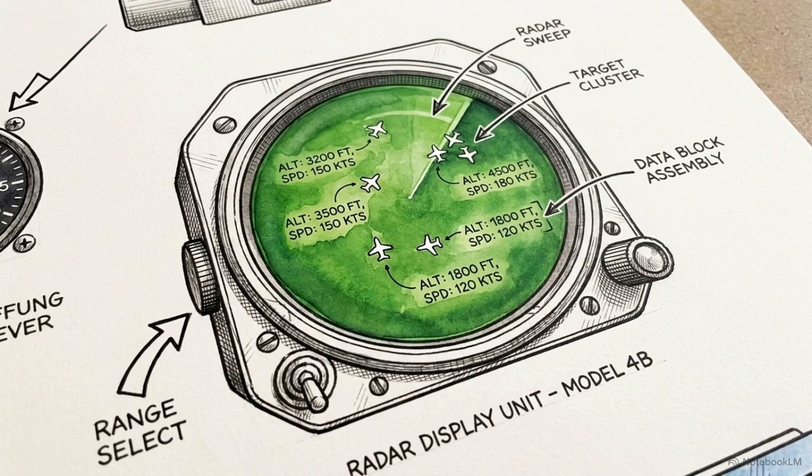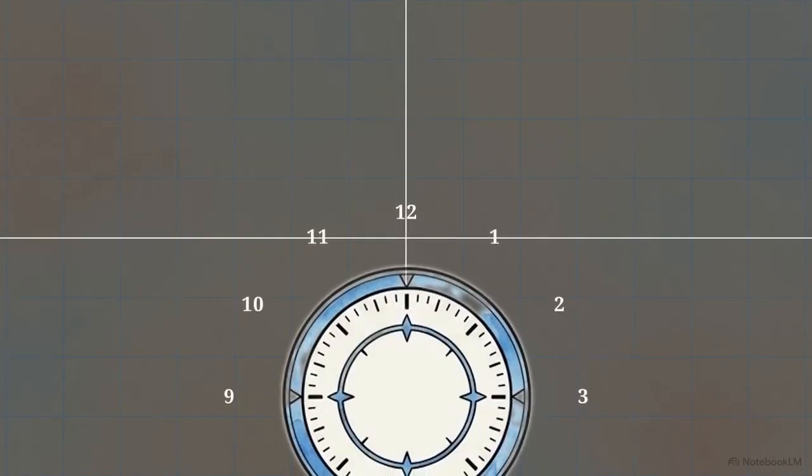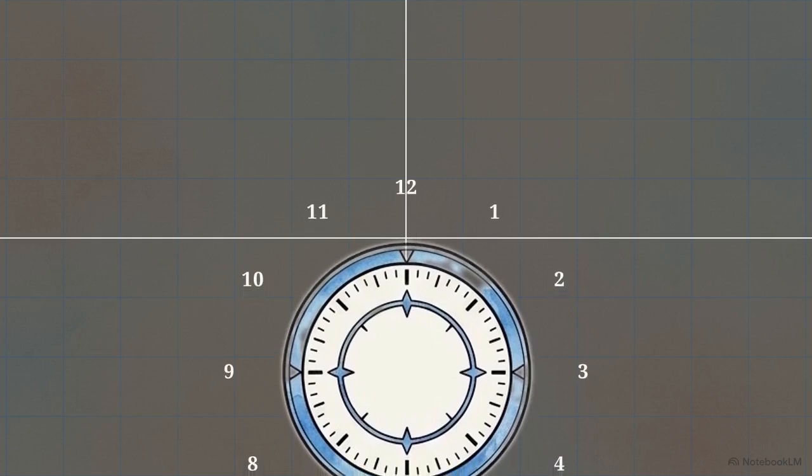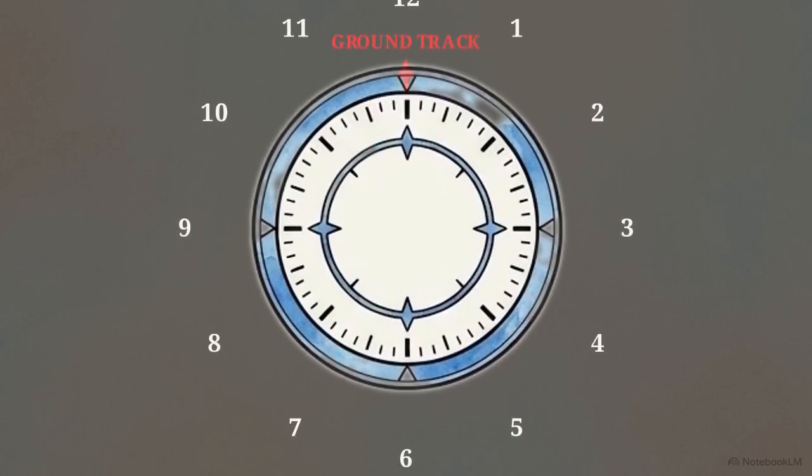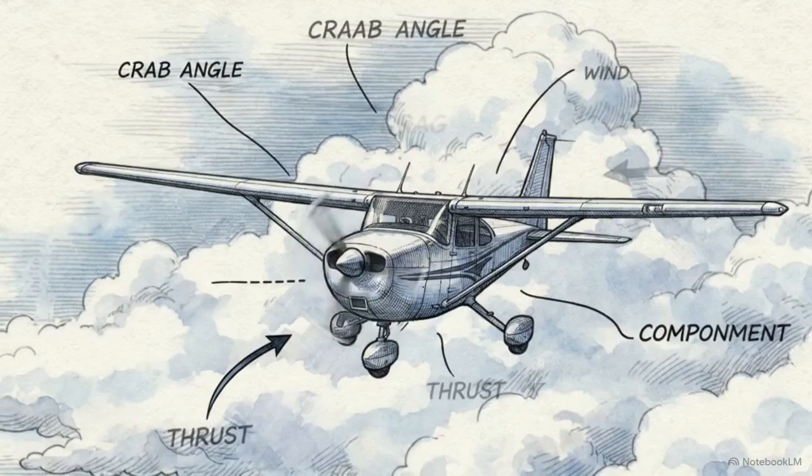Controlled airspaces operate on a completely different model. Within Class B, C, or D airspace, ATC utilizes terminal radar to actively assign altitudes and headings, manually sequencing incoming traffic. When ATC calls out approaching traffic using the clock system, advising a pilot of an aircraft at their 2 o'clock position, they are referencing the radar screen.